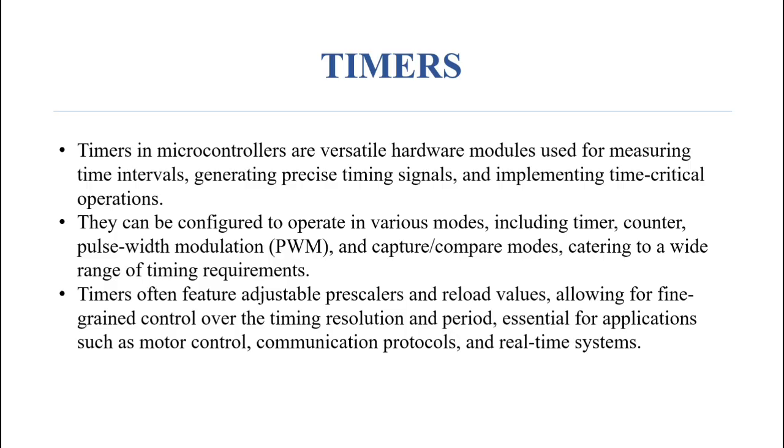PWM means pulse width modulation, which is operated by the pulse. Timers often feature adjustable prescaler and reload values, allowing fine-grained control over the timing resolution and period. Essential for applications such as motor control, communication protocols, and real-time systems.